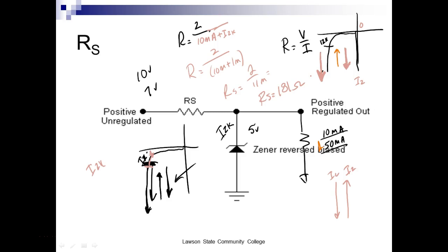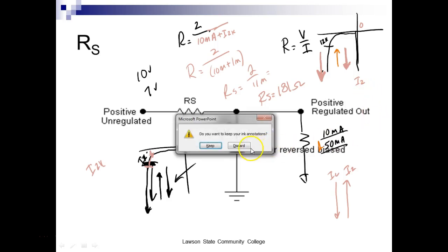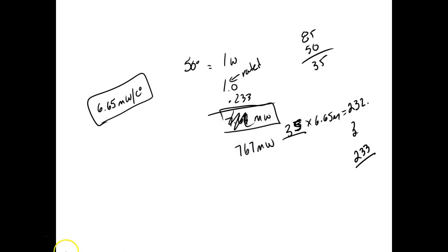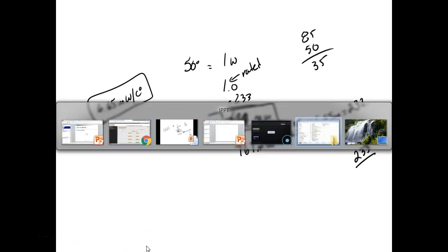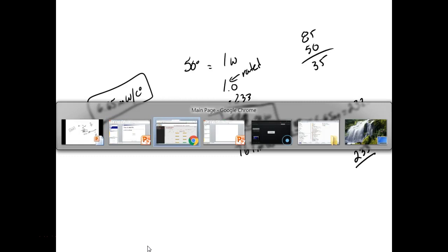Always. If it fell on a 2.2K ohm resistor, I would always go down to the next standard value. Everybody okay? And then I would check the tolerance. If my tolerance turned up to be greater than 181 ohms, I would go down one more value. You understand? So we check our tolerance. So let's see what size resistor I would use. Anybody know what standard resistor? Where are we going to find this information? Probably on Blackboard, probably in reference material.